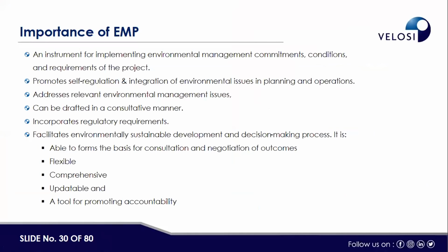Okay. First question. Does CEMP also cover the IEE or EIA for any in-progress project? No, as I mentioned in my slide, first of all we have to develop the EIA. For example, there are different stages of the project. For example, the FEED stage. The FEED stage is basically an initial design stage. So in that stage, the environmental impact assessment is required. And when the project goes into the detail stage, detail engineering or the EPC phase, then we have to develop an update of the EIA, and then for the construction phase, we have to develop the CEMP. And before the start of the operation, we have to develop the OEMP. And if that project also includes demolition, then we have to cover a DEMP as well. Otherwise, the construction will only deal with the CEMP, and the OEMP will only deal with the operation phase.